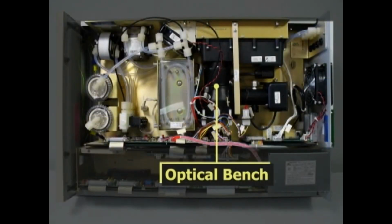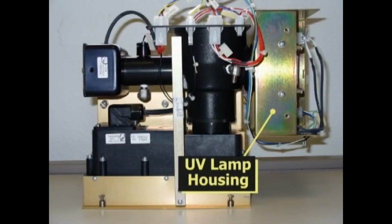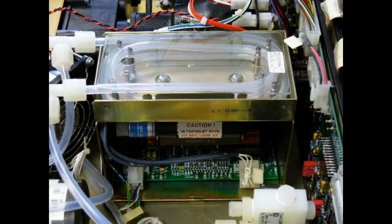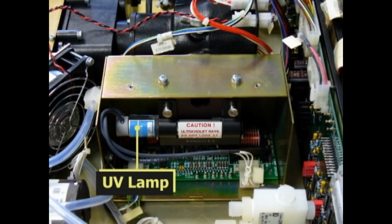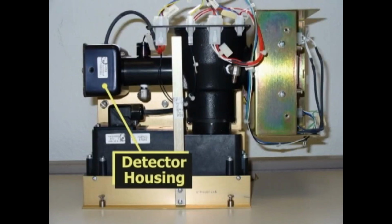The optical bench is the heart of the analyzer and where all measurement occurs. A metal door on the UV lamp housing shields the user's eyes from the damaging effects of ultraviolet radiation. The UV lamp and lamp drive board are located inside. The reference detector is mounted inside the detector housing.